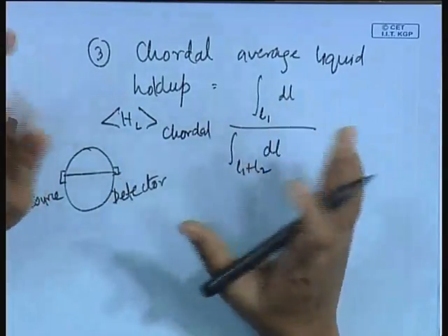So, from there again with certain mathematical techniques etc., we can find out the amount of the light ray which has been transmitted, and it can be related to the void fraction. Okay. So, therefore, when the volume average and the area average are not possible, then we go for the Chordal average void fraction, and it is usually converted to the area average values by two techniques. One is we can do extensive mathematical manipulations.